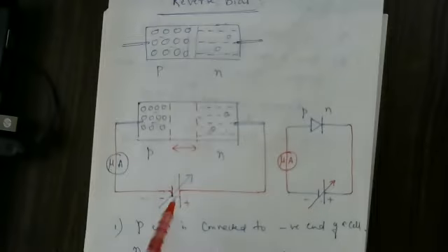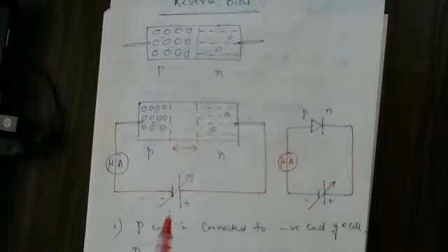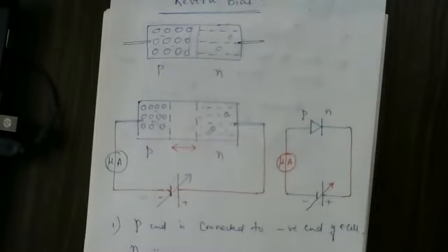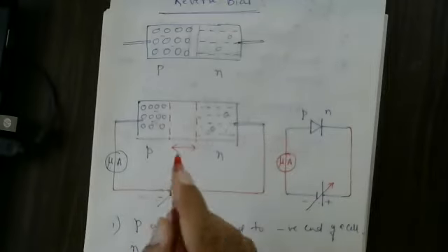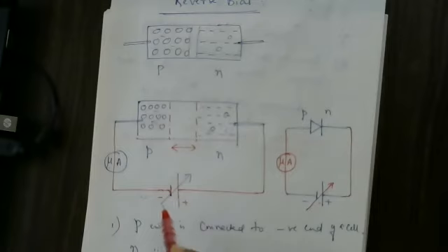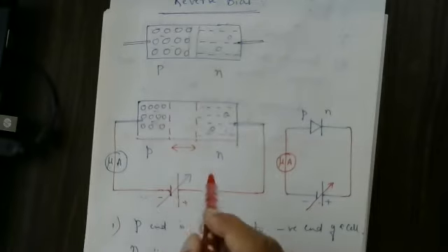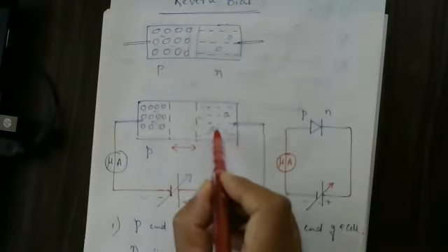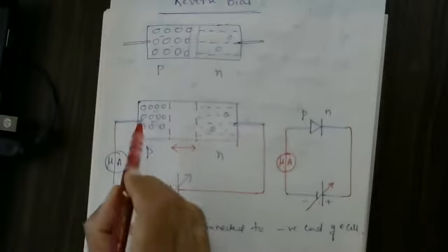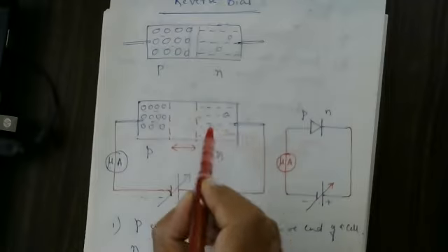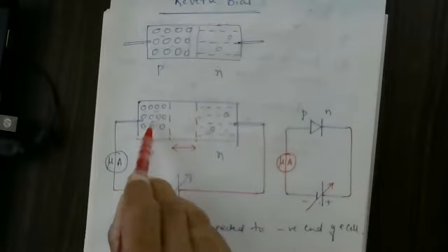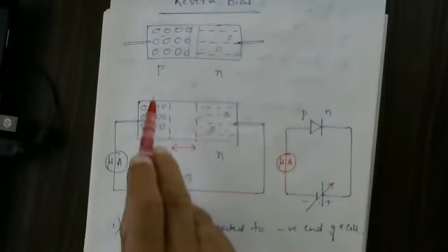So one more question: what do you mean by breakdown voltage? In the reverse bias condition, as you go on increasing the externally applied voltage more and more, at a particular voltage more covalent bonds in the N variety and more covalent bonds in the P variety break up. Hence the minority charge carriers in the N variety and in the P variety increase.